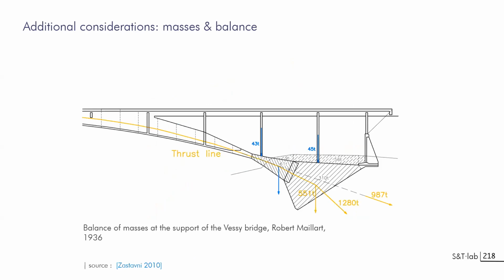There's another example coming from practice from Robert Maillart. These are the foundation blocks of the Salginatobel Bridge. You see that the problem in such an arch is that you have quite horizontal reaction forces. And if you are just pushing in this direction, you have something that's too horizontal to be supported by the ground. So the strategy is that you have to change the direction of these forces. What has been classically used in masonry bridges is to combine this thrust line with the weight of a massive block foundation. So you have a first change of direction here and a second change of direction here that will give you a new direction for the forces. This one is less horizontal, more vertical, and this time it can be sustained by the structure. So this is about playing with loading to equilibrate the system.